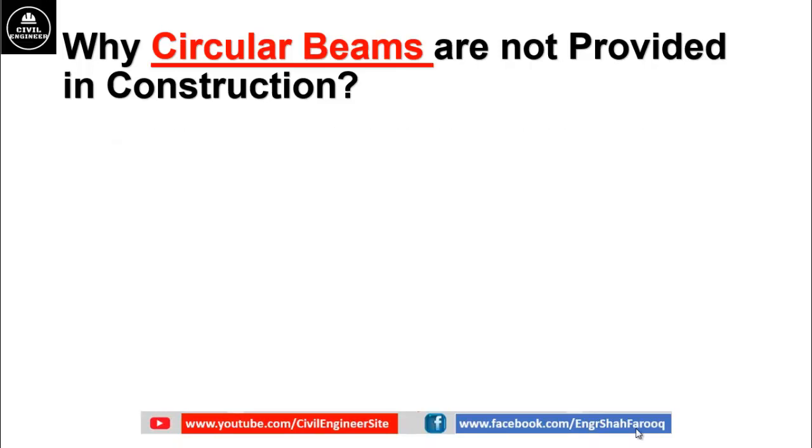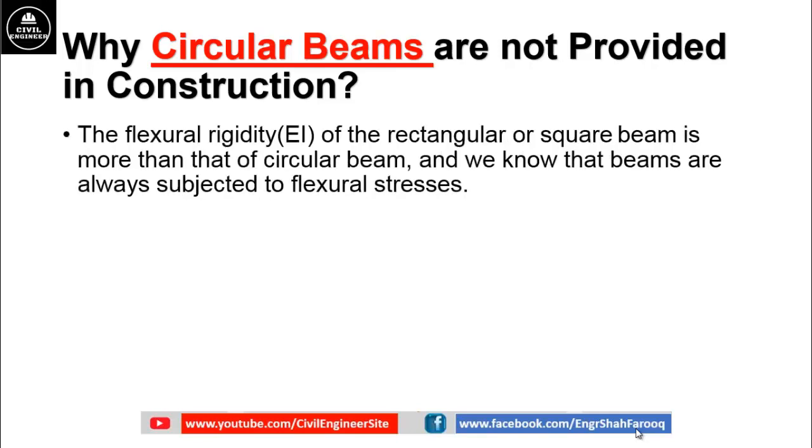Beams are flexural members and are subjected to bending stresses or flexural stresses. The flexural stress of a beam is dependent upon moment of inertia. Here you can see that flexural stress is inversely proportional to moment of inertia. Now to increase flexural strength and decrease flexural stress, you have to provide a beam having a larger moment of inertia.